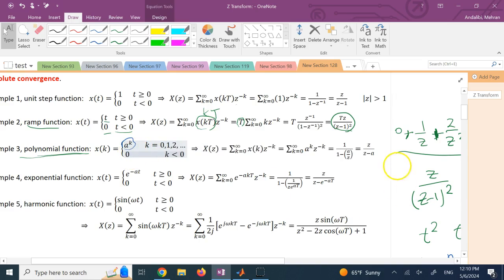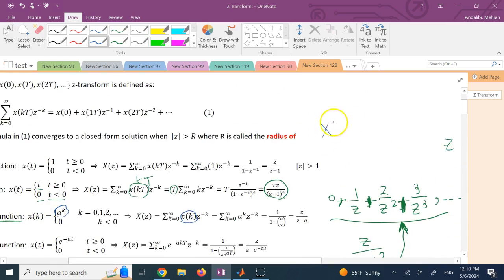So what's the answer? So in this case, x of k or kt. Now you might say, where is t gone? In general, in discrete time, many times you see that x of kt is replaced by x of k. If you see that, do not be surprised. They do not put that t always, okay? It has this t implicitly in it, so when we say k, it means the kth sample. What time is it? K times t, of course. But if you see, instead of x of kt, there is only x of k, it doesn't mean they forgot the t. That means t is implicit.